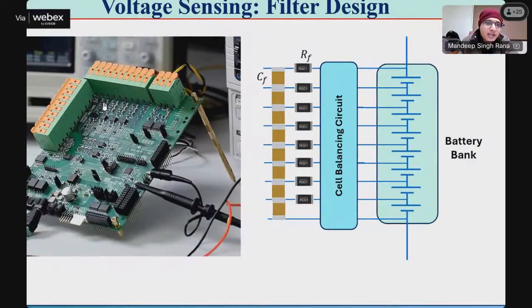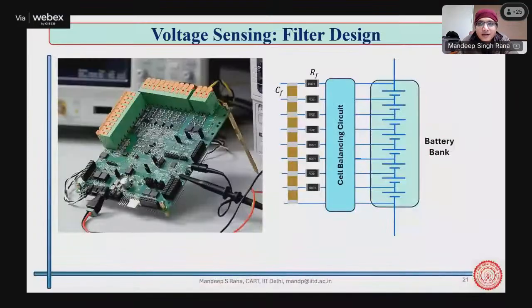Because there are many cells and you want to look at many such voltage and related data. With that data, you want to filter it with RC or second order filters sitting near your input, and it is very common practice. Whenever you look at an AFE card, the first layer is these RC components.